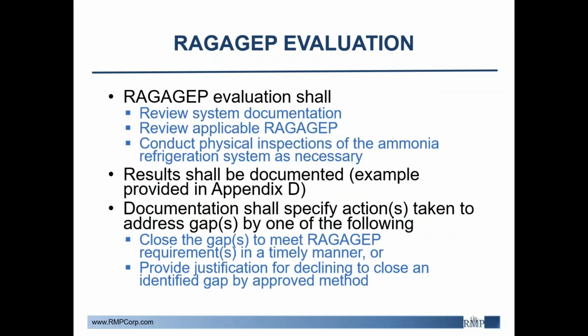So RAGAGEP evaluation is going to review system documentation, applicable RAGAGEP, so that would be your standards that you're measuring it against, and any kind of physical inspections necessary on the system. So when you're verifying materials or valve placement and whatnot, that would be your walkthrough. All the results should be documented.